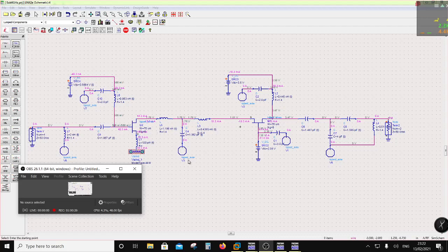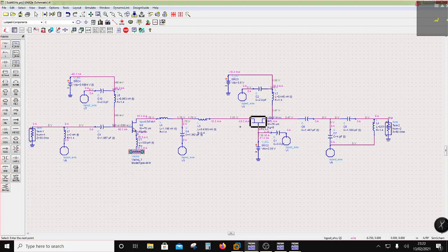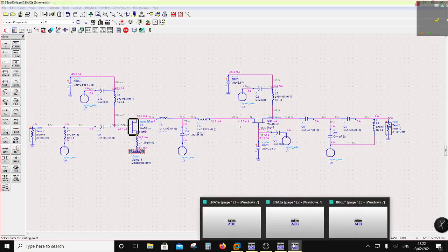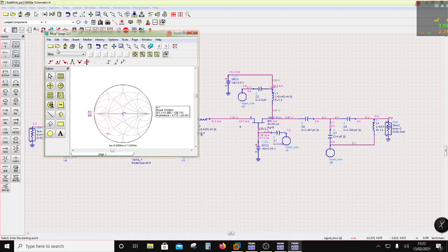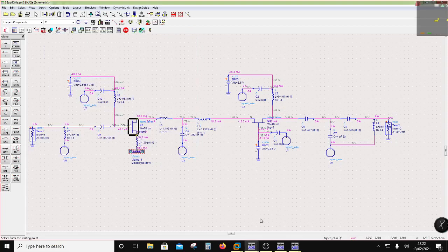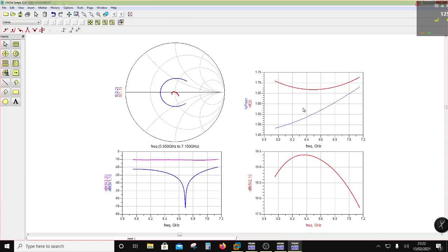Okay, great. And one more thing I want to point out: when people do cascode, if they come from an analog background, they just put this transistor on top of that transistor without anything in between. At low frequencies, it doesn't matter, but at high frequencies, this will not work, right? So that's the only key point I can give here. Okay, so I'm going to stop here, and that's your two-stage LNA with a response which is like this, right?